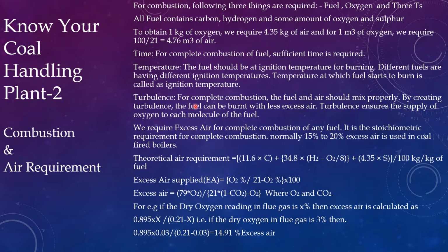Then the third one is turbulence. For complete combustion, the fuel and air should mix properly. By creating turbulence, the fuel can be burnt with excess air. Turbulence ensures the supply of oxygen to each molecule of the fuel and helps complete combustion.